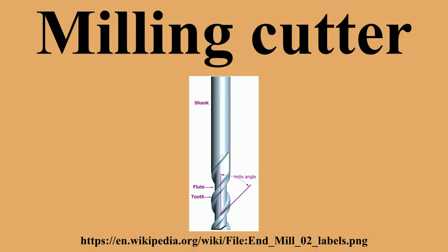Shank. The shank is the cylindrical part of the tool which is used to hold and locate it in the tool holder. A shank may be perfectly round and held by friction, or it may have a welded flat, where a set screw, also known as a grub screw, makes contact for increased torque without the tool slipping. The diameter may be different from the diameter of the cutting part of the tool, so that it can be held by a standard tool holder.